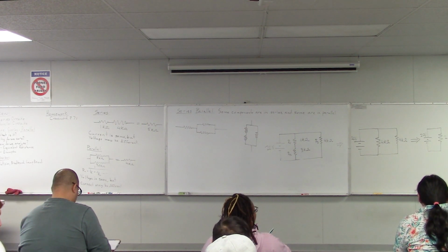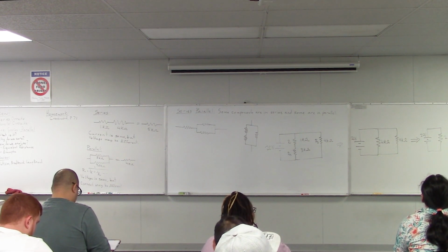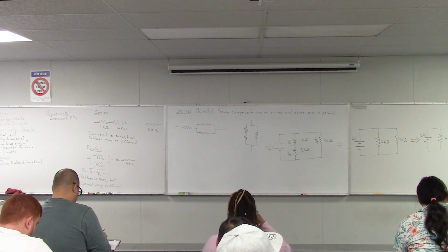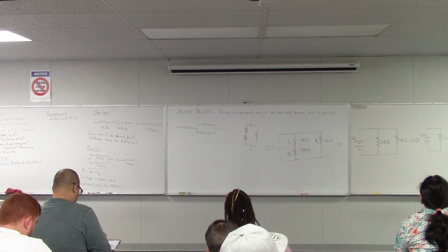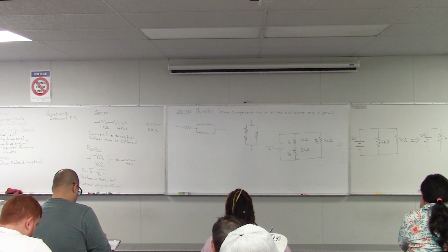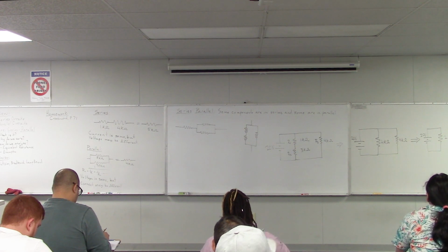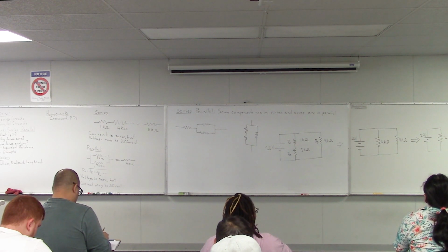And remember, the unit is just the raw unit, whatever that is. So in this case, it's just amps. It's not milliamps, it's not kiloamps, it's nothing else. It's just amps. So this is 0.01 amps. Now, once I have that, I can use my engineering notation to convert it, if I want. So if I wanted to convert this to milliamps, what would that be? 10. Yeah, I would multiply that by 1,000 or move the decimal point 3 places to the right, and that would give me 10 milliamps. So that's the total current for this circuit. So does anybody have any questions about how we found that?